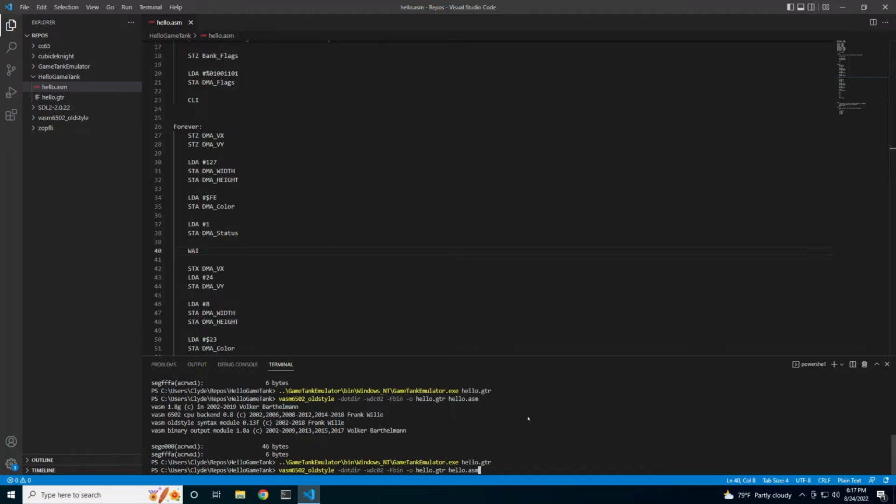While the blitter is drawing, modifying its registers will interfere with the drawing operation, so we'll pause the CPU until an interrupt happens. Changing these registers during drawing won't damage the hardware or anything, but at the time of this recording, the emulator isn't designed to present the behavior accurately.